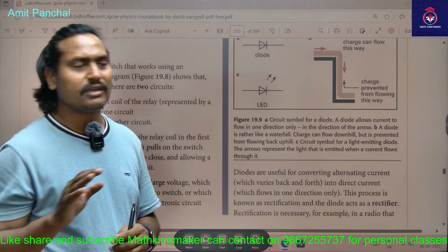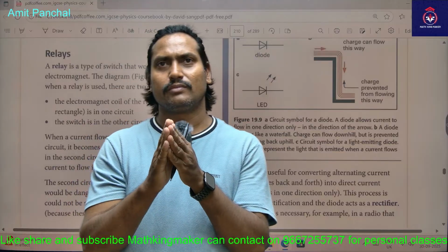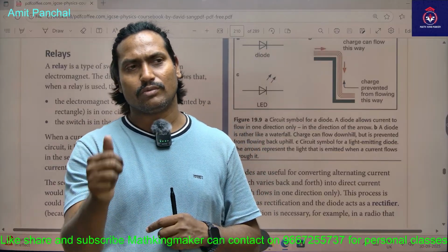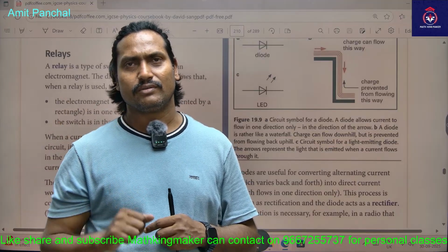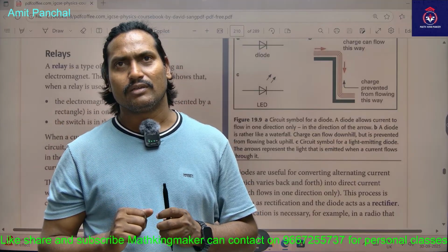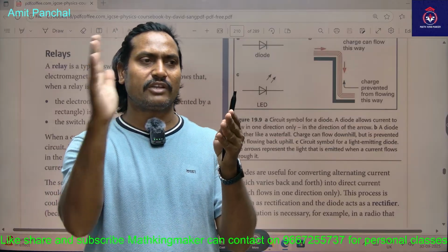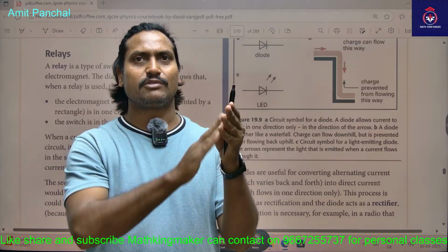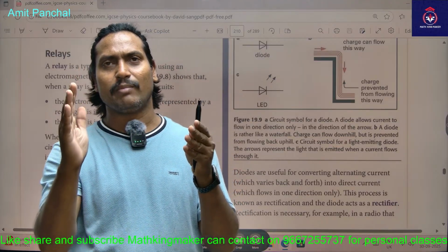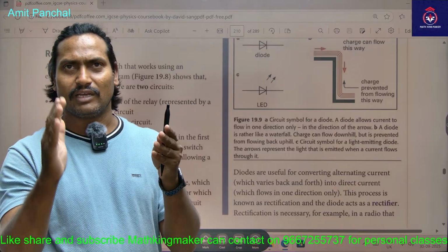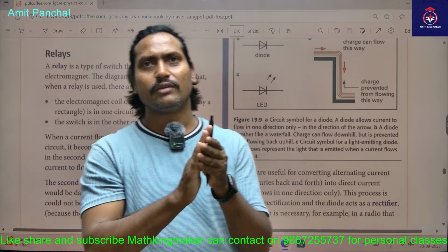So what is happening there? There is a hammer. As you press the button, that hammer gets magnetized. And there is a drum. The drum is a ferrous metal, and the hammer becomes an electromagnet, so it strikes the drum.